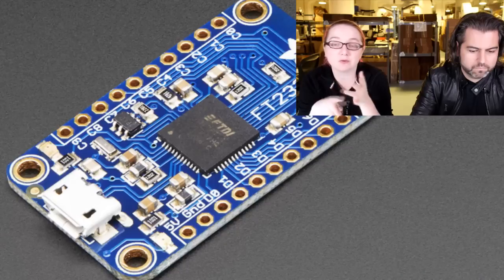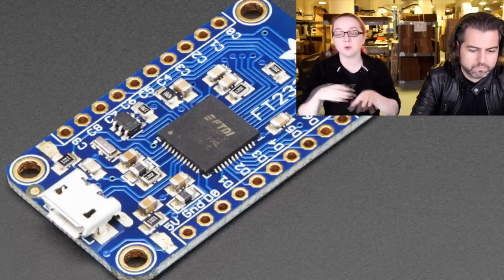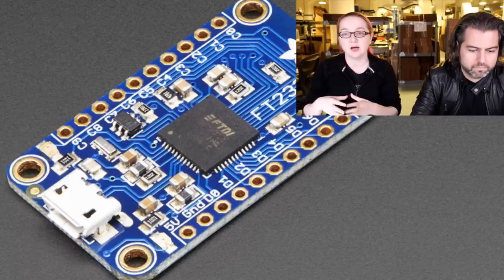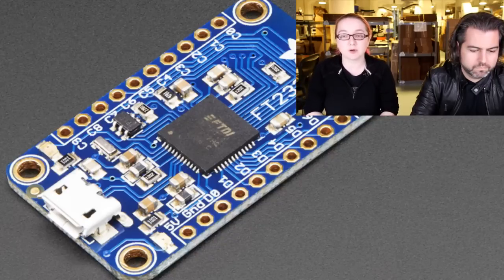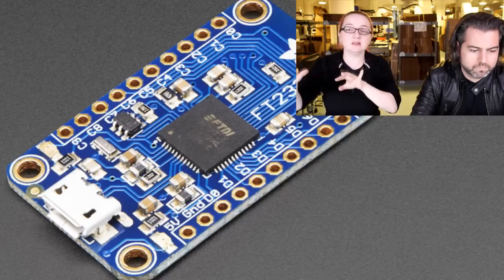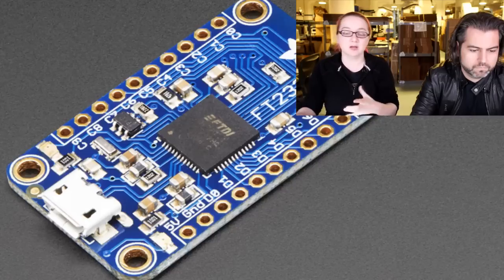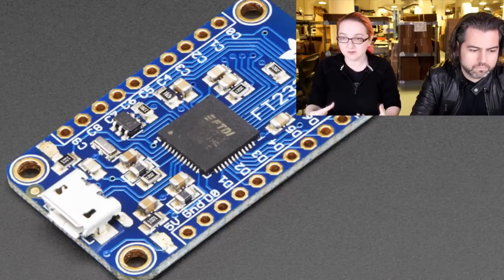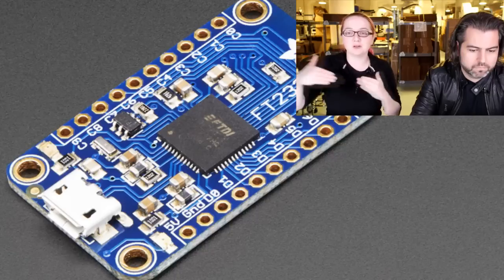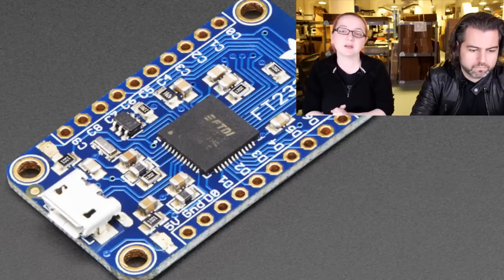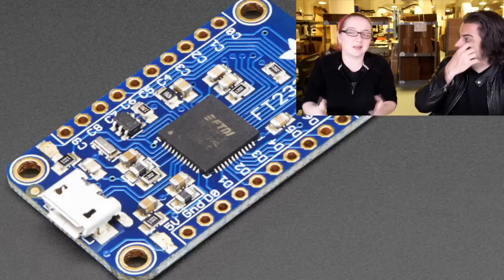And you can use Mac, Windows, or Linux to communicate with this chip and then quickly interact with I2C or SPI devices without having to set up an Arduino and open up the Arduino IDE. If you want to just write the code raw in Python, like turning on LEDs or connecting to NeoPixels or displaying something or reading an I2C sensor, this is a fun chip. I know it's a really vague description. It's like, what is it? It's not a microcontroller. It's this kind of bridge between USB and other stuff, but it's nice because there are drivers for all these operating systems, and it's so general purpose.